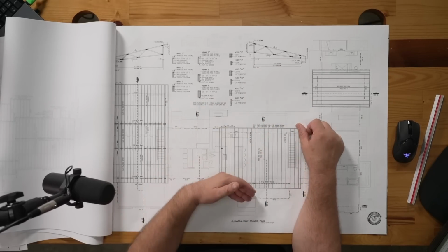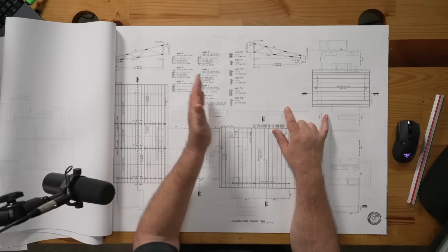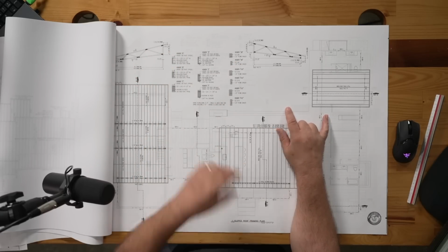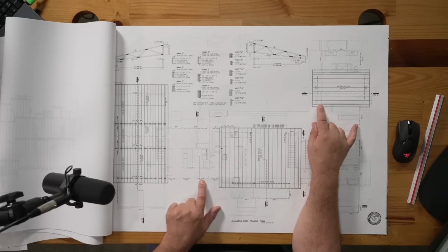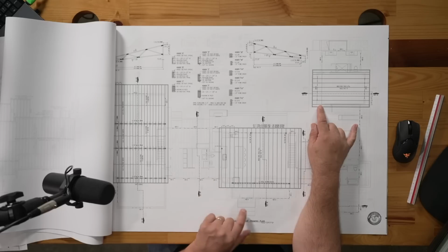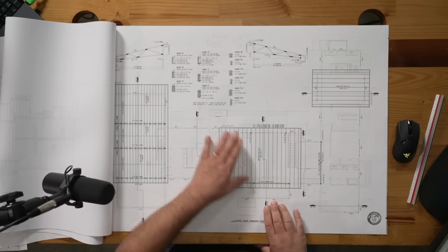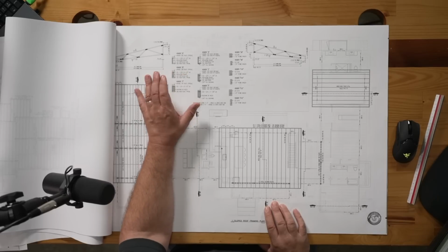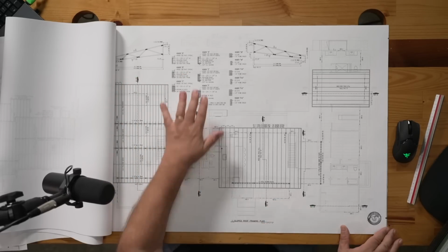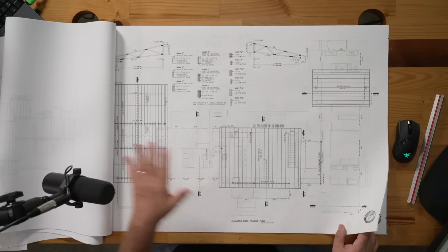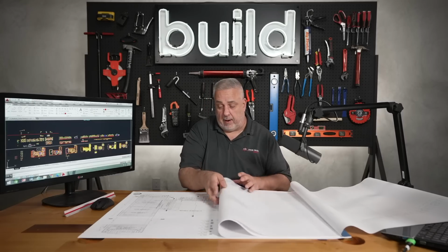As far as headers go, I create a header schedule here, and you see headers A, B, C, all the way through H12. If I go out to the drawings here, you'll see there's header B, header A for those windows, header A, header B, A. So they simply look at header B and reference it, go over here to the legend, and they know exactly what header is being placed in there. And again, that's on the same page, so we're not shifting through all these pages when these guys are doing the layout for that.